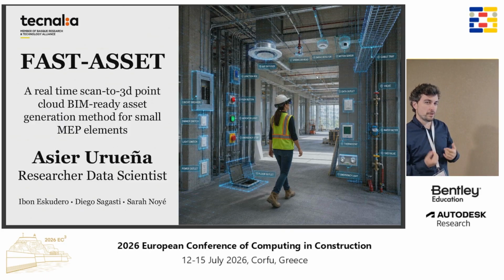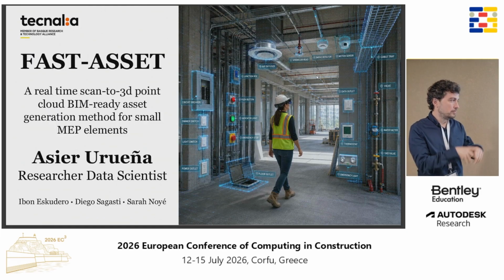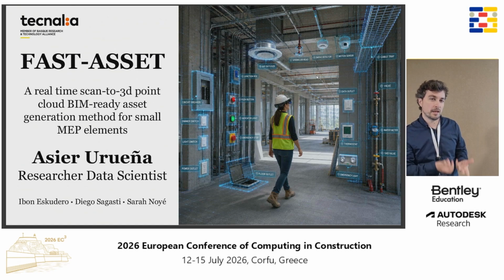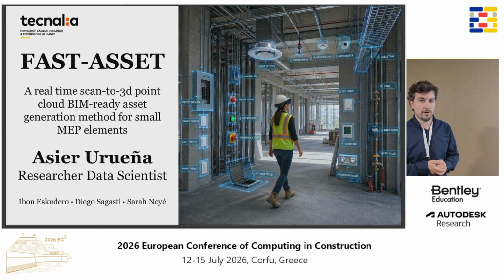The problem with traditional Scan-to-BIM technologies is that you capture the whole point cloud, go to the office, and then segment it. Sometimes you have to come back and take more captures because you left something behind, and there is also the processing time in the office.